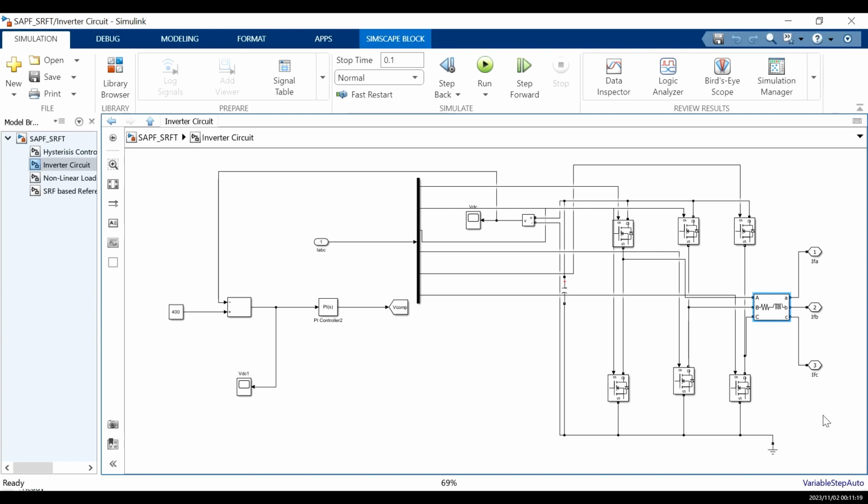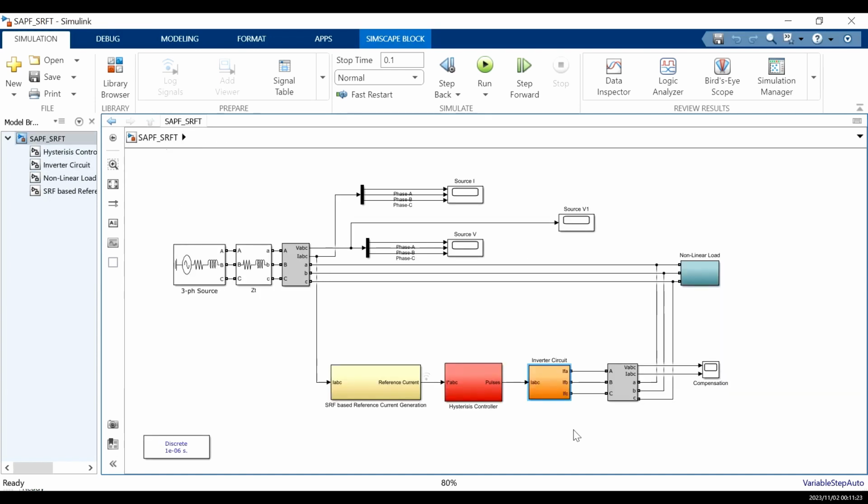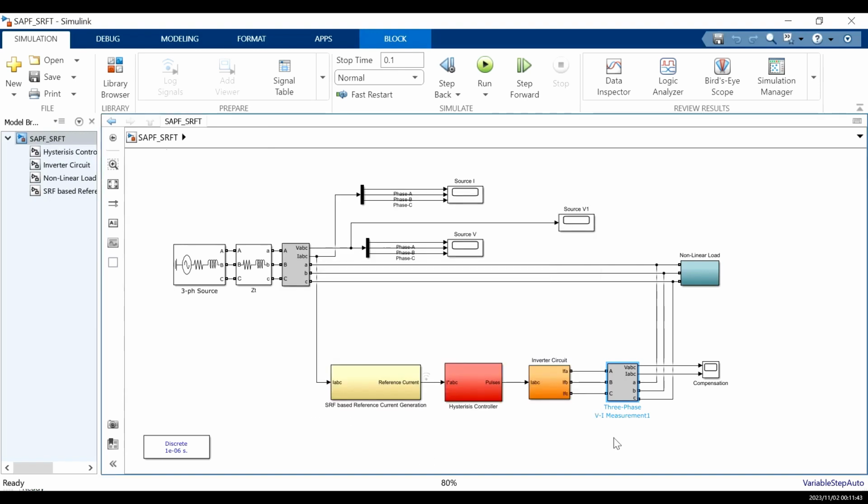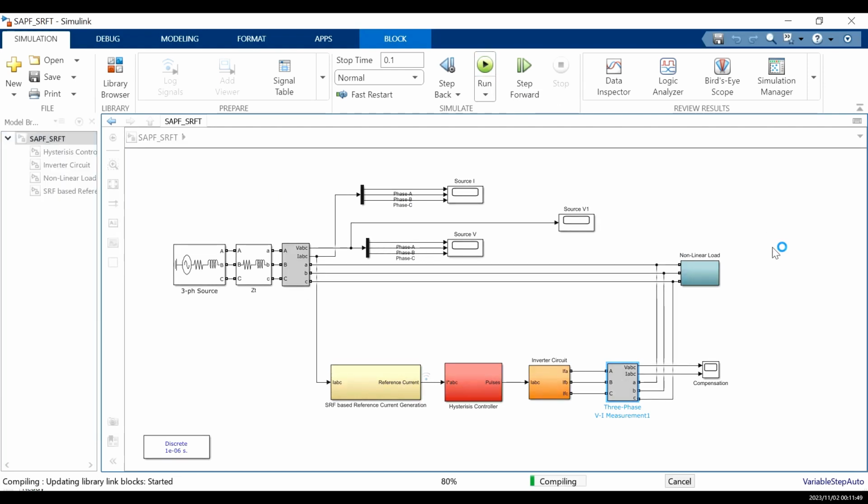The basic configuration of a three-phase VSI consists of 6 power electronic switches, typically insulated gate bipolar transistors (IGBTs) or metal oxide semiconductor field effect transistors (MOSFETs), arranged in an H-bridge topology. The switches are controlled by PWM signals to create a simulated sinusoidal output waveform. By modulating the width of the pulses, the VSI generates a finely controlled AC output voltage, which can be adjusted to match the desired frequency and amplitude.